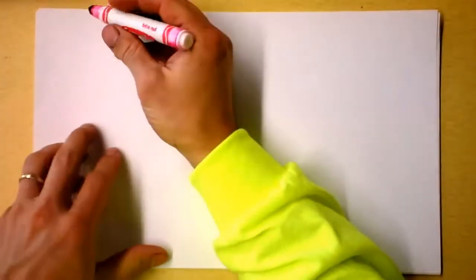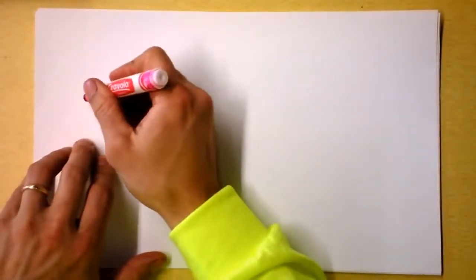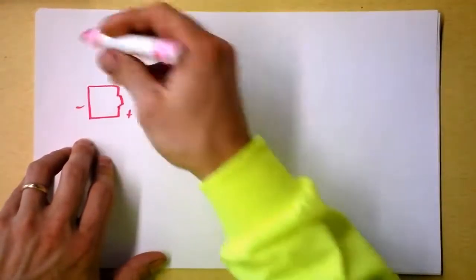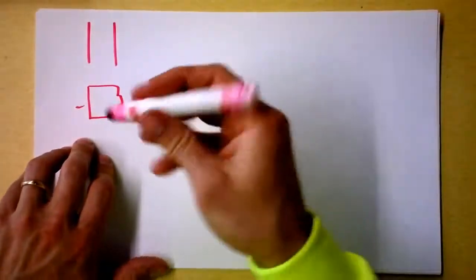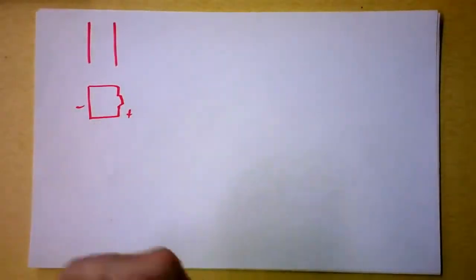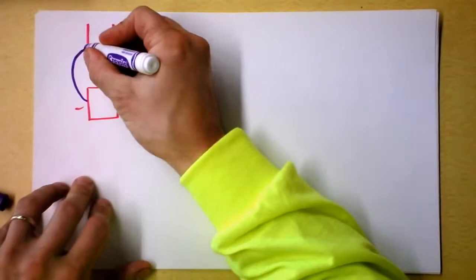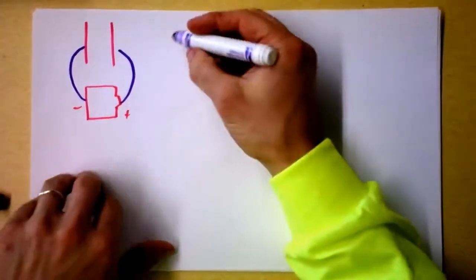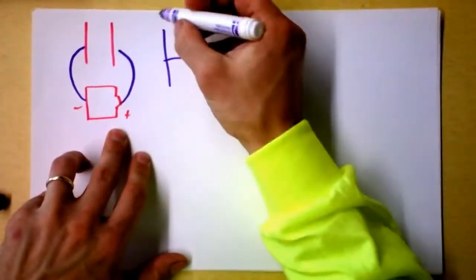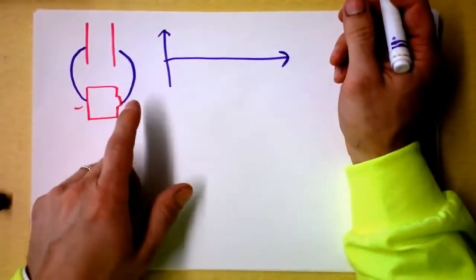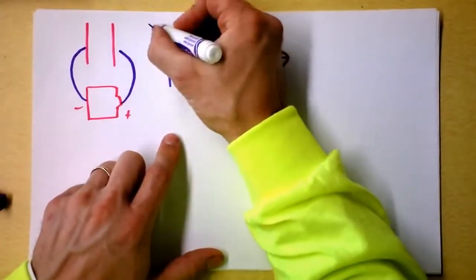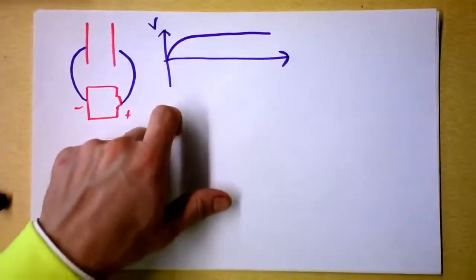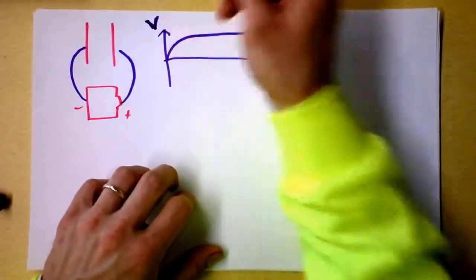Hey, if I hook up a capacitor to a battery, let's say I've got this D battery here, and this side's positive and this side's negative, and here I have a parallel plate capacitor, and my intention is to put a wire between here and a wire between here. As soon as I connect that, the voltage on the capacitor will gradually increase like this. Voltage will go whoop, like this, and approach some maximum level, probably the voltage of the battery, if this is a function of time.